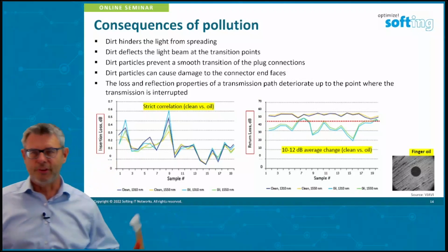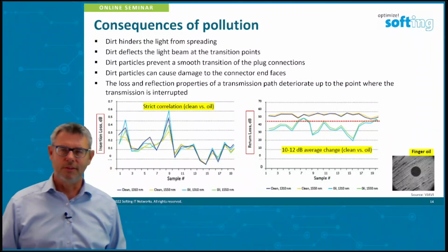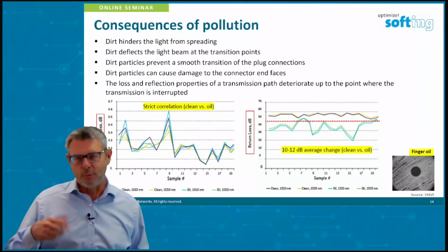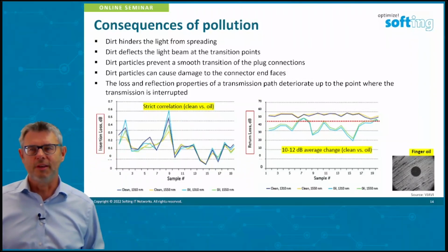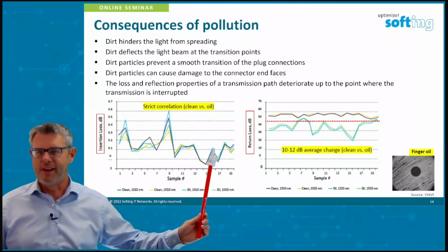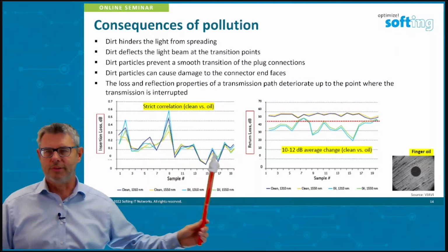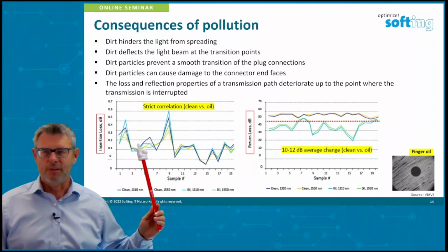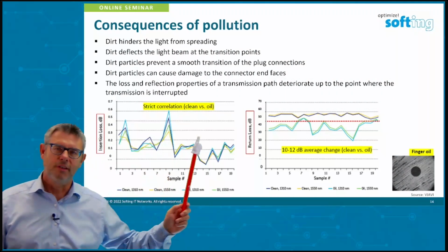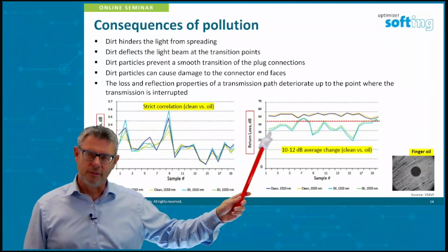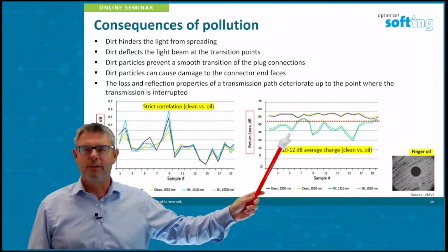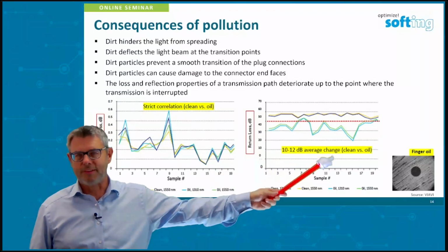And it's called finger oil, what you see now on the connector. If you reconnect this connection and repeat the measurement, first of all, you will see that the attenuation gets higher, so we are missing more light traveling through this connection. But the worst experience is that the measurement results of the reflection just dropped, and they dropped dramatically.